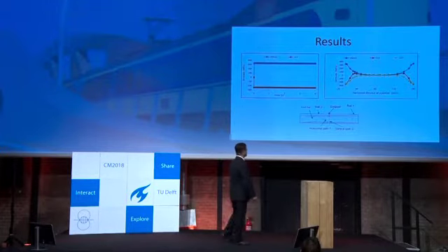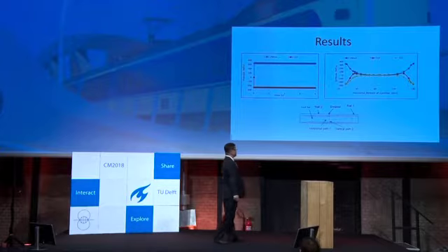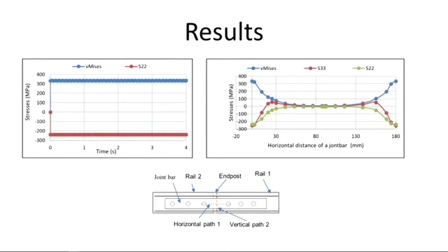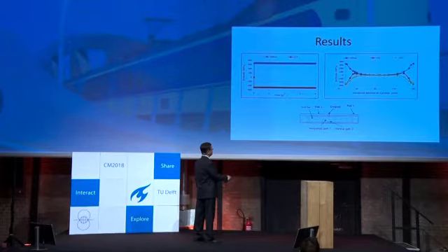Away from displacement, if we go to the stress side, what is happening? The stress value here and through this line and so on. I put two stress components: one is the vertical stress, S22, and another is the von Mises stress. We can see, at this point over this time period of 4 seconds, it is the same all over. If we see what is going on from here to here, in the middle this is not so important.